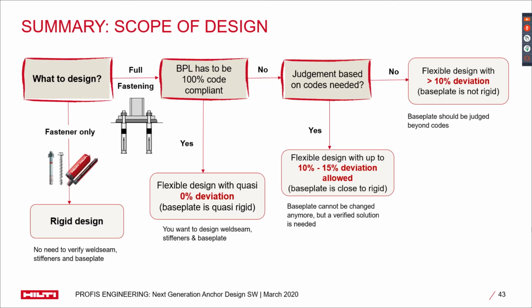So now we know how to design anchor connections using Profis Engineering. Firstly, it depends on what you want to design. If you just want to design the anchors and will design the base plates separately, you can carry out the same rigid design, similar to Profis Anchor.